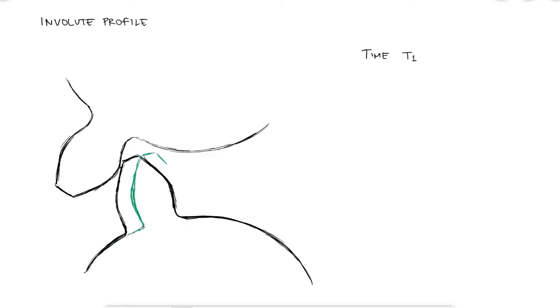This shape would guarantee that the point of contact between two teeth, one from each gear of gears in contact, occurs where the two surfaces are tangent to each other. The reason I say would guarantee instead of stating it as a fact is that this only happens for perfectly formed, perfectly smooth, and infinitely rigid teeth, which of course is not the case.